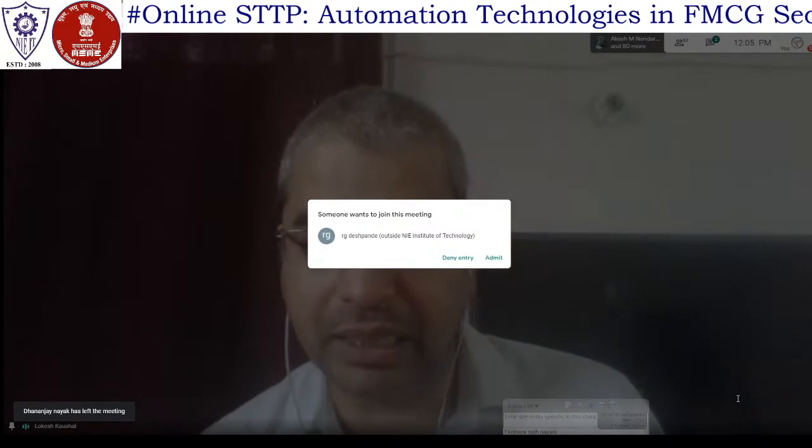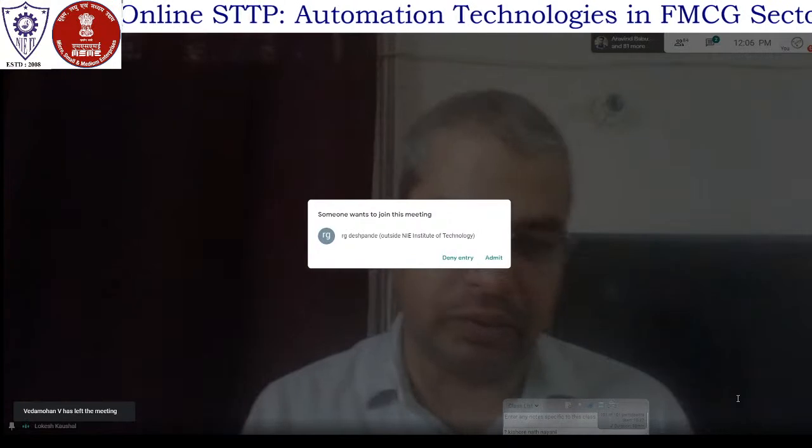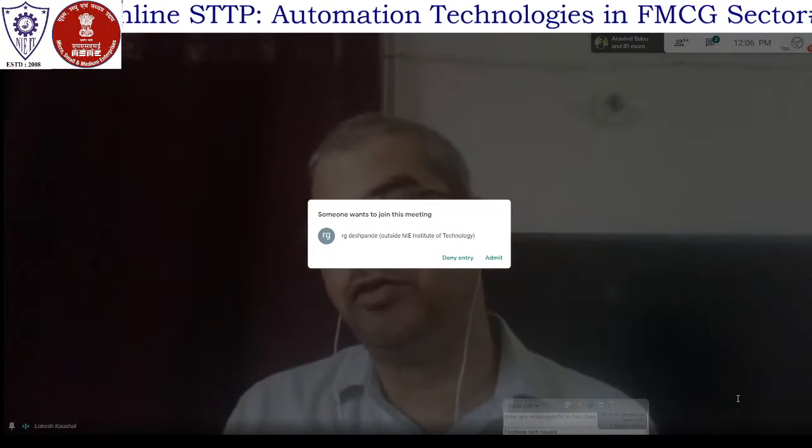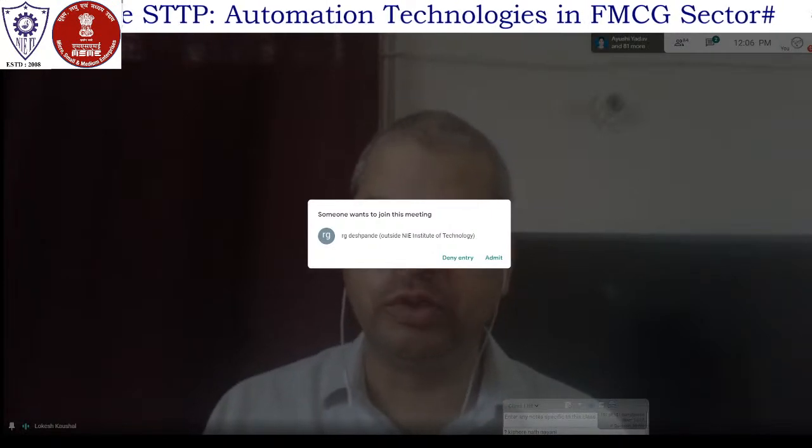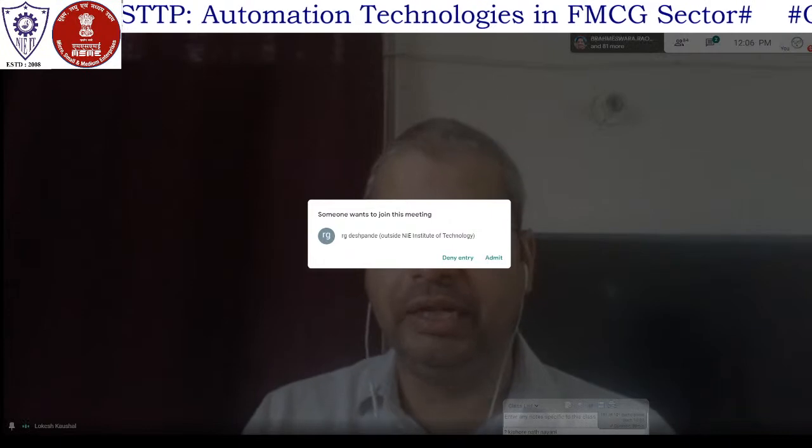Sir, instead of servo motor, can we use synchronous motors? By that, Mr. Patel, you mean these independent cart motion solutions? Yes, sir, definitely. A quick comparison: when you are using a servo motor for a linear movement, you're either going for a linear servo motor, or you will use a rotary servo motor and put some sort of transmission mechanism in front of it to make it linear. That is exactly the space where you could utilize these linear synchronous motors or independent cart solutions.